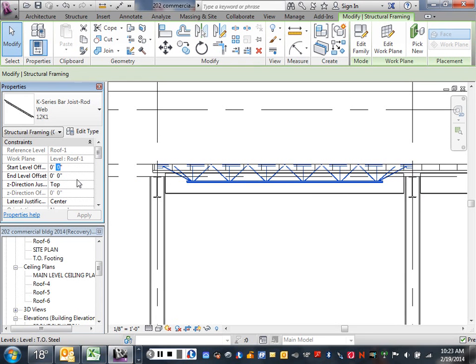And the bar joist is going to be, if I set the top of the bar joist at 8 inches down, it's going to be at the same level as the steel. And the bar joist has how thick a bearing point on the end? 2.5 inches, right? So I want it up 2.5 inches from the steel. So this should be down then minus 5.5, because 5.5 plus 2.5 would be 8, right? So I'm only going to come down 5.5 inches, both at the start and at the end.